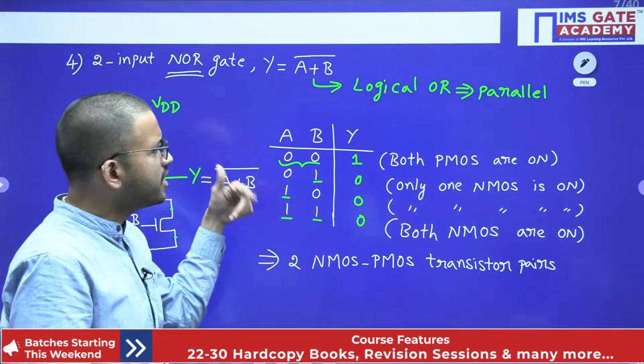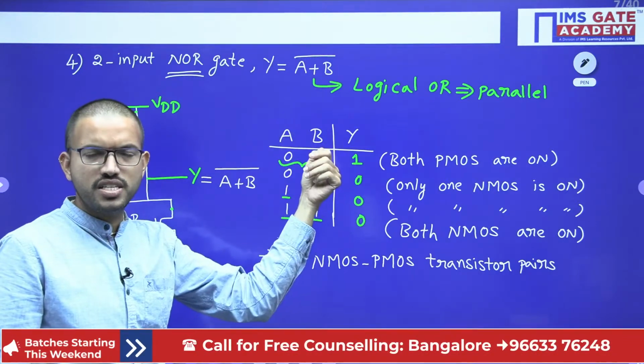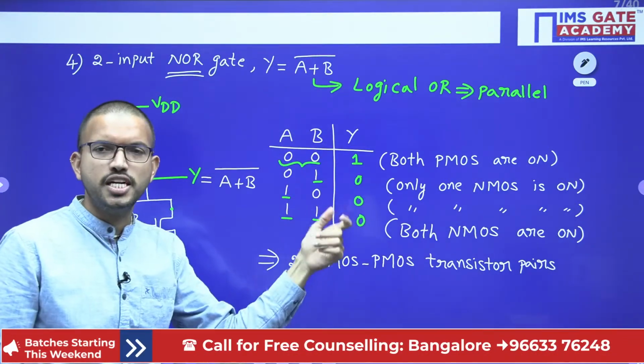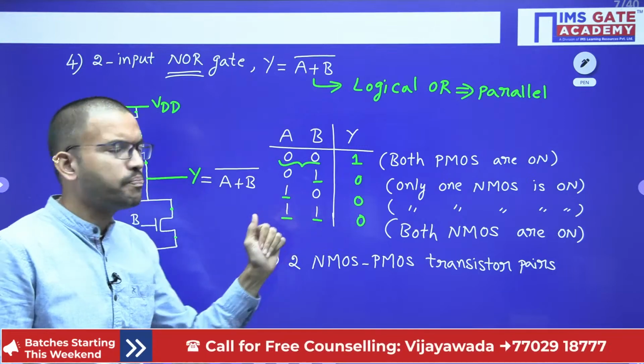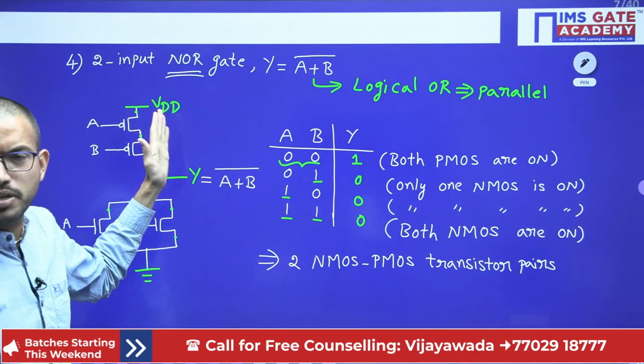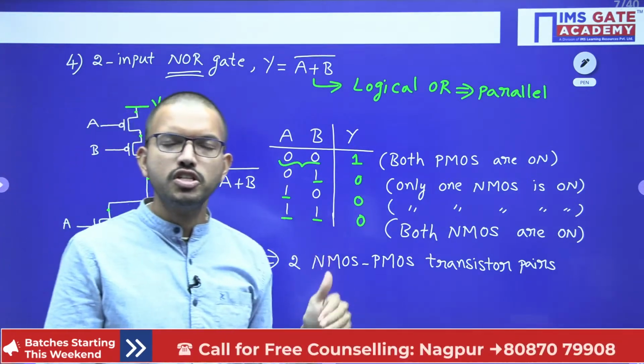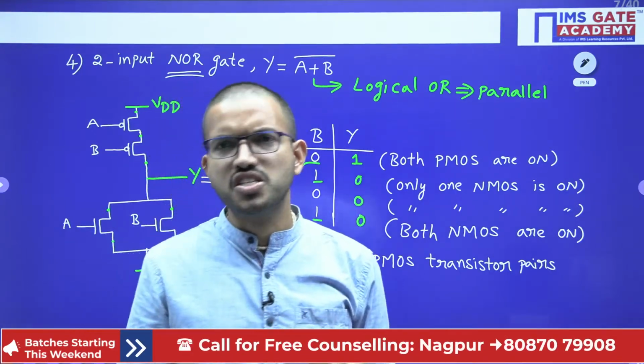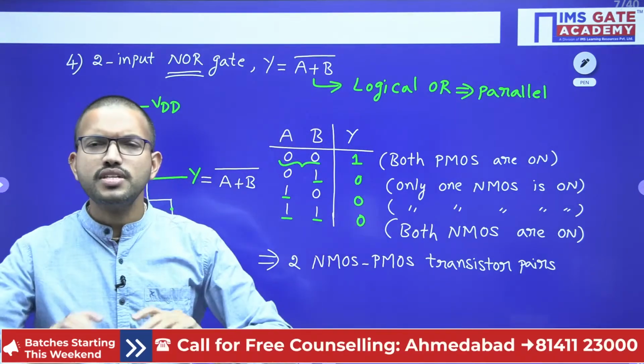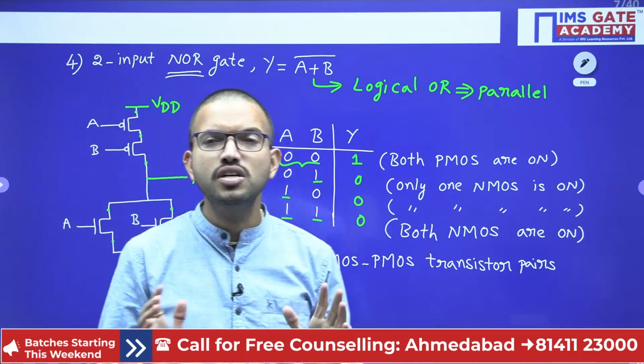Whereas in the other logic families, which I mentioned in the beginning of this session, we are using one resistor permanently. Because of that, throughout the operation you are having static power dissipation, whereas in the CMOS logic, we are able to reduce the power dissipation.